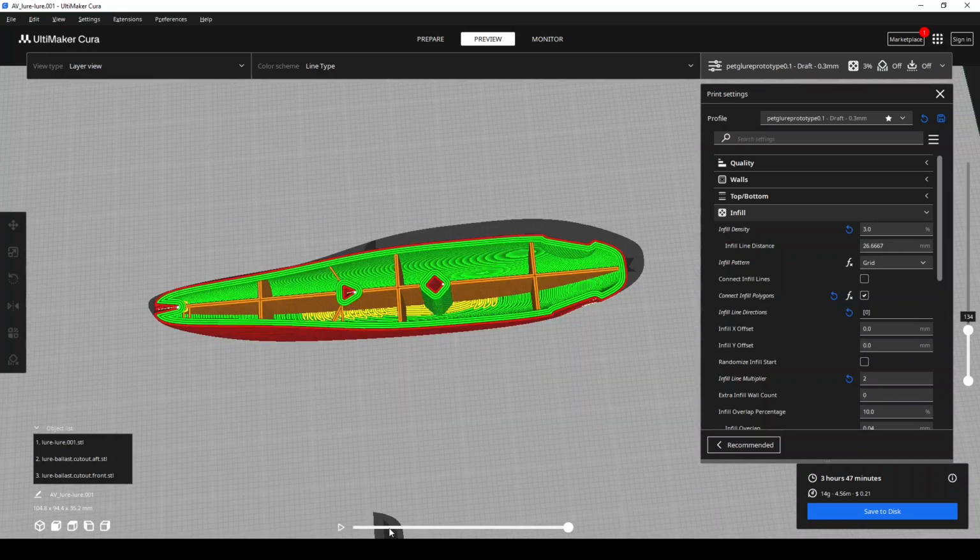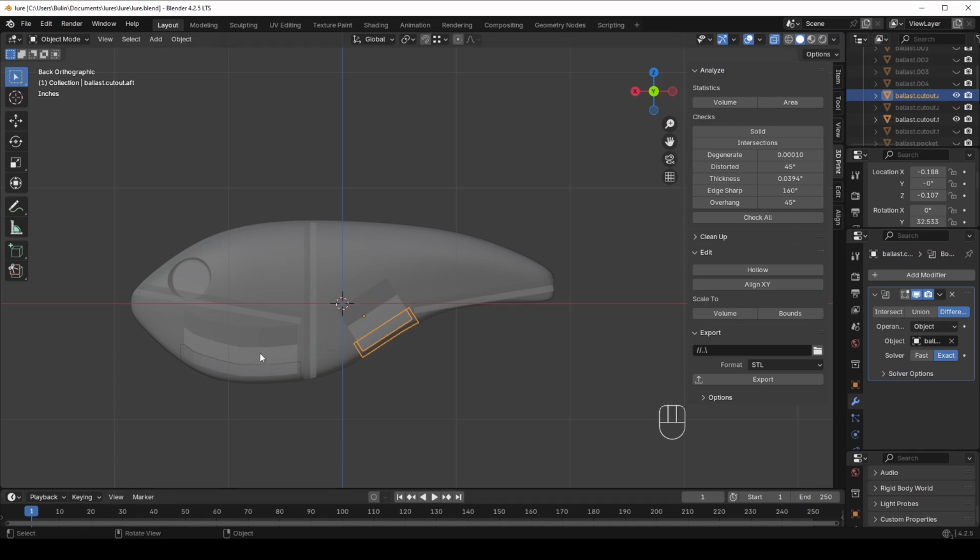The more ballast that you can get down low, the more you can lower that center of gravity. And the lower you can get the center of gravity, and the higher you can get the center of buoyancy, and you get those two in a tug of war against each other, it keeps your lure in the floating position that you want it to be, and it'll be more stable whether you're reeling it in faster or it's got erratic action or whatever.